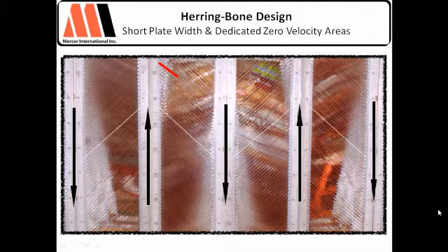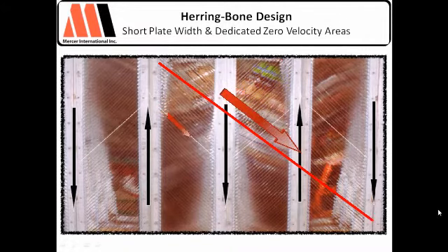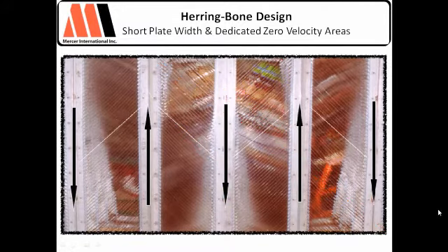So instead of solids up here having to fall way down a plate, ramping up and plugging, now it only has to fall 24 inches. That's important. The other thing to look for that we've incorporated is to be able to process solids. Will your coalescer, the one that you have or the one that you're looking to get, process solids?